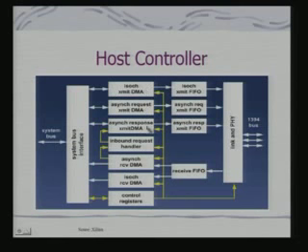Other buses will also have a conceptually similar interface architecture. Here you find that for each one of them I have indicated the DMA channel, and you have the control registers. In fact, these control registers essentially manage the overall DMA transfers. If it is a DMA request, so that the processor should relinquish the bus and data gets transferred, that information will be generated from here, and the location where the data has to go, etc., all this information will come from the control registers.